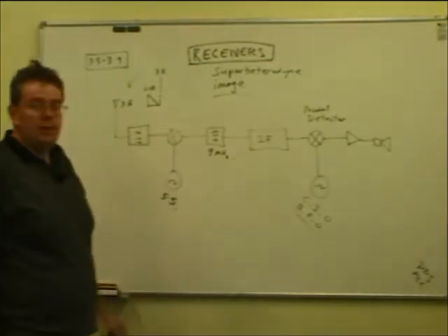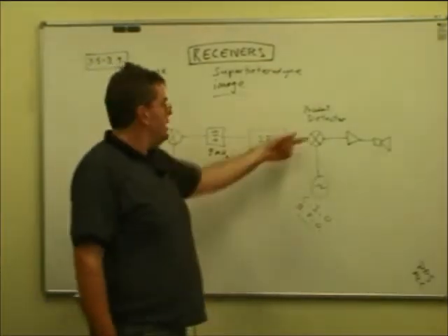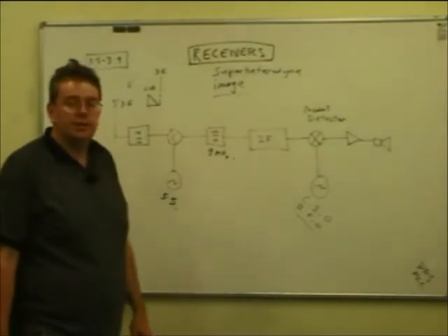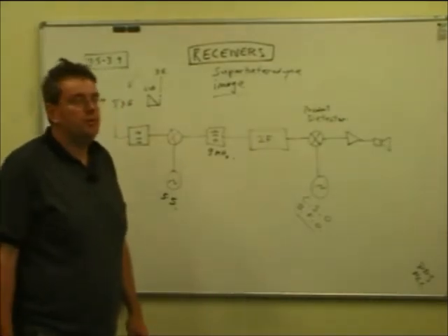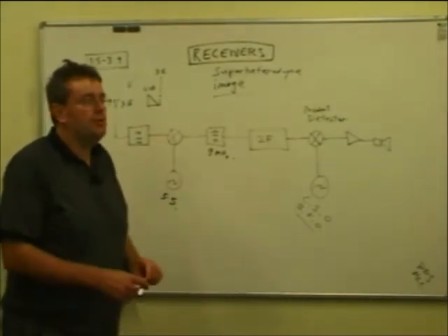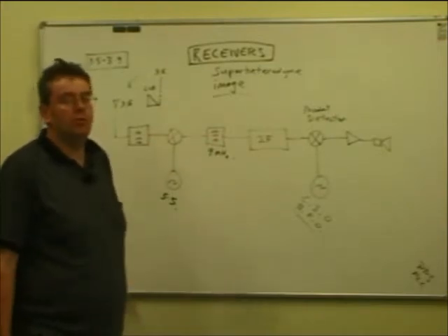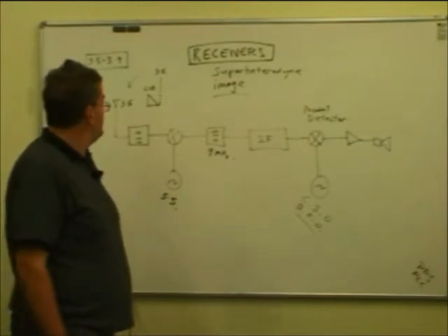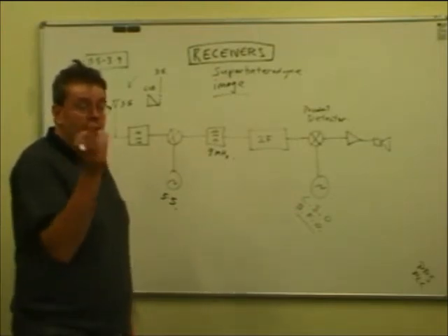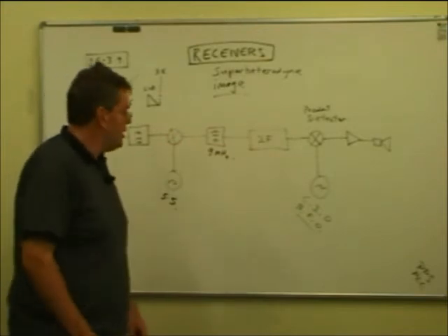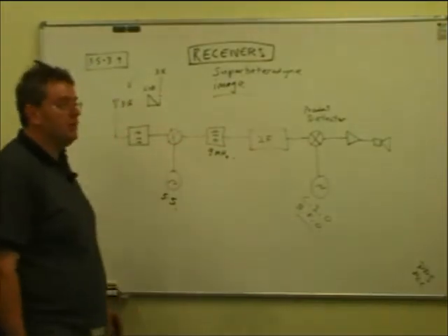If we put a single sideband signal into an AM detector with no carrier re-injected, it sounds awful. This is what people used to call duck talk in the old days when they tried to receive single sideband on their AM-only receivers. You got this sort of horrible noise. What in effect it is, is the signals within the single sideband signal combining with each other to produce sound signals, and it doesn't sound very nice. You certainly can't understand it.